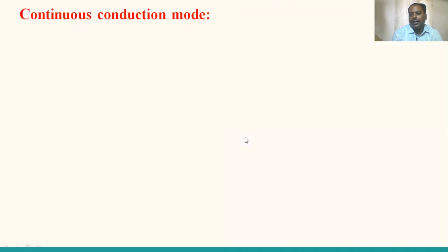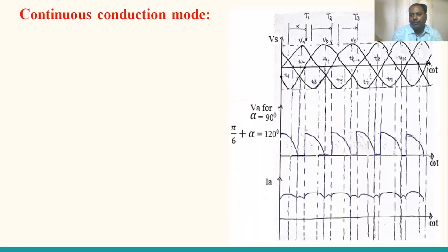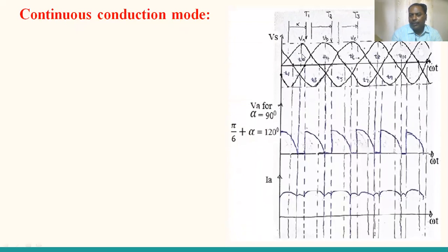Okay, so you can observe here, in the upper half thyristor T1, in the lower half D3 is coming into action. It commenced at 120 degrees, so the average output voltage will appear like that. This will continue up to this point, which is hardly 180 plus 30, 210 degrees. This is omega t4. At 210 degrees, what will happen?